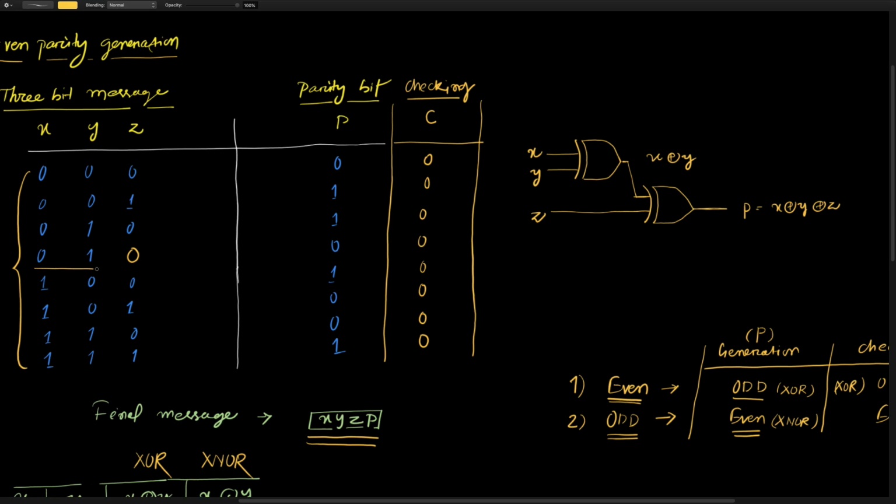For this combination your message contains an odd number of ones, so your XOR value would be 1. So you will be notified that the message received is not according to the parity followed, and you can say that the message received is wrong. Whereas if the message is not wrong, and whatever is sent is received, you'll get 0, and you can say that the checking is done and there is no error.